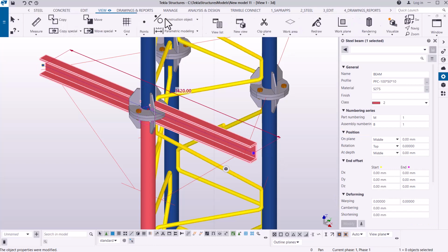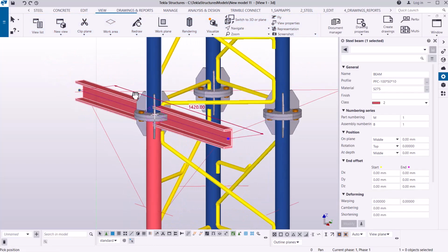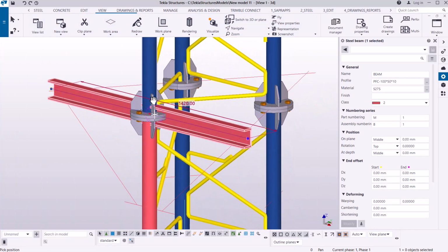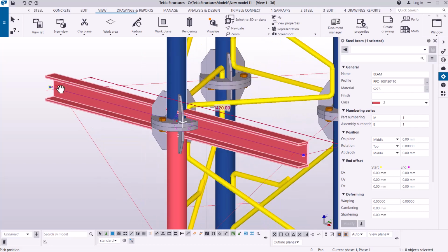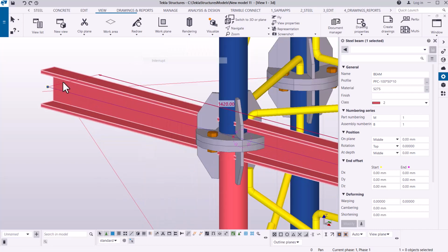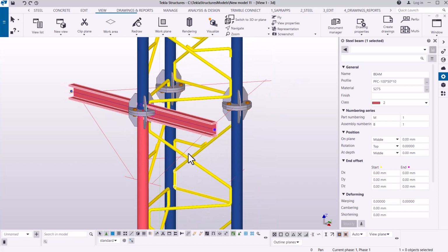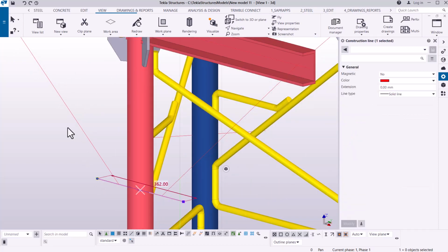So what I'm going to do is try to rotate this and pick attain rotation by left clicking, and we have this in place right at the center. So we can either leave it where it is, or we can bring it down somewhere here so that the top end flushes with our member, but we can just leave it where it is. And now we have this member at the bottom end here. This member's length is 362.